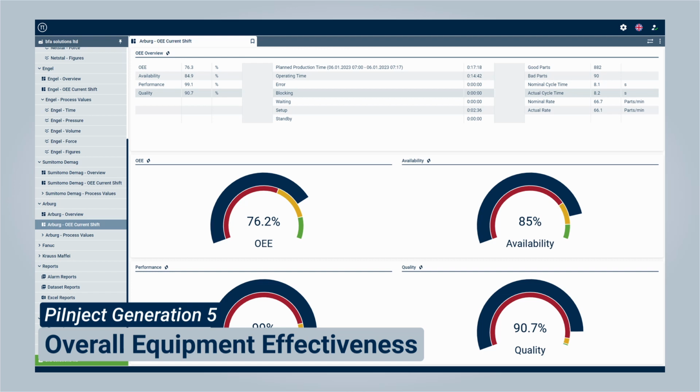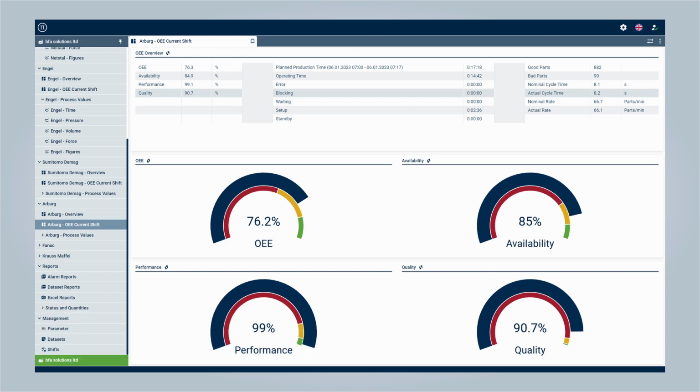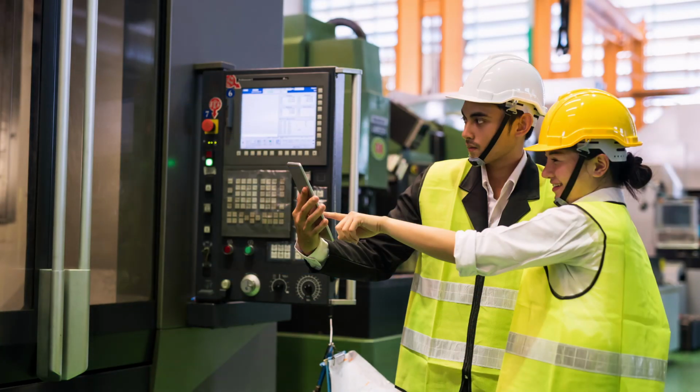The values can be used to identify specific inefficiencies in a process, such as frequent machine stops that reduce availability, slow cycle times that reduce performance, or high levels of defects that reduce the quality parameter. By tracking OEE, informed decisions can be made about how to optimize the processes and operations and with it increase the profit.